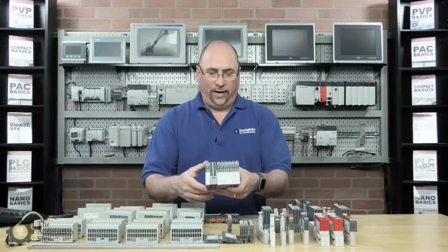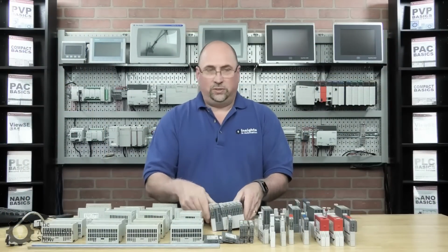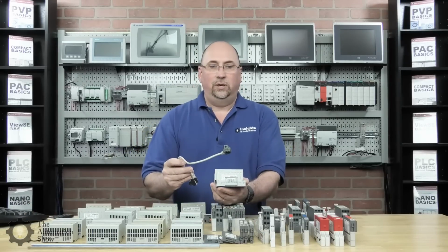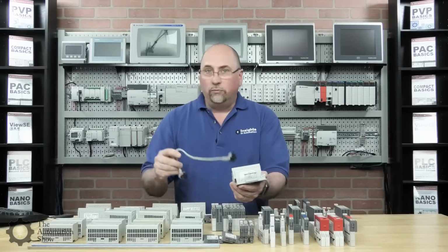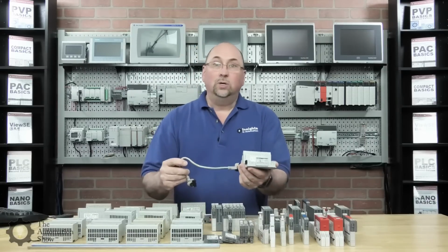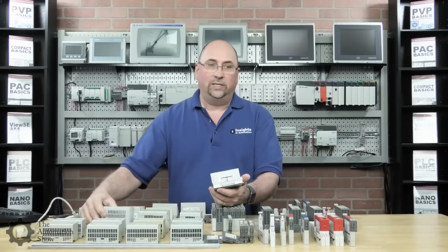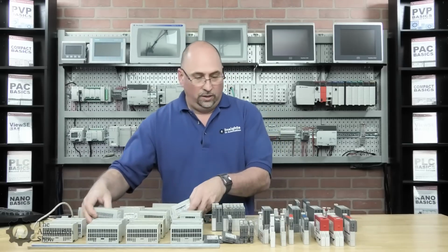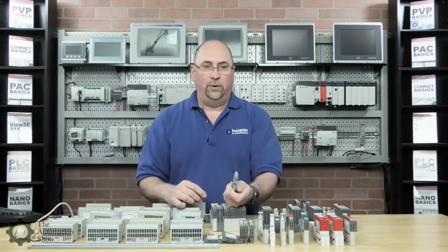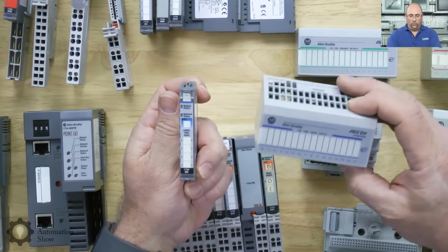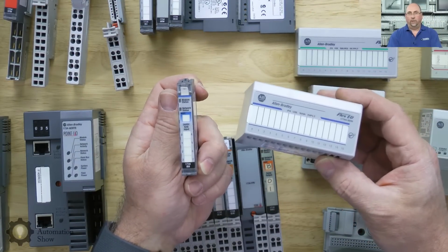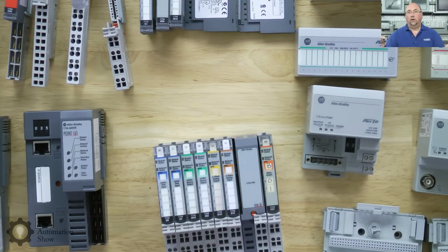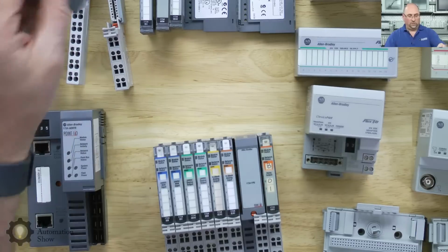And while we're talking about that, Flex-IO only supports 8 modules in a string. Now you can use that expansion cable to break that string into 2. So I could have 4 and 4 or 6 and 2, but that's it. Every network adapter for the Flex-IO can only handle 8 modules. Now those modules are higher density than the Point I/O. We were talking about the 8 point being the highest density I could have. Well, it's very common in Flex-IO to have 16 point. So you may only have 8 modules, but you're getting 16 modules' worth of inputs into a system.